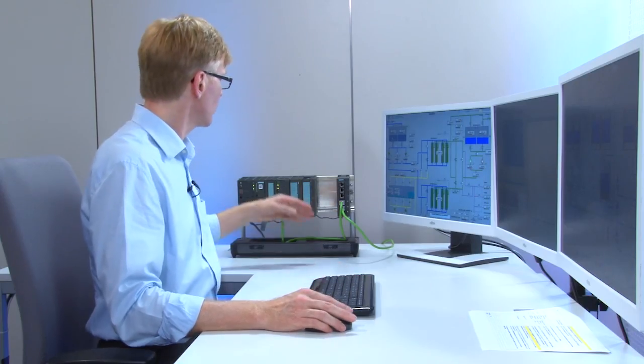As you can see, in just a few minutes we have configured a WinCC control center and its basic functions and started it up using ST7cc. A majority of the elements required in WinCC were automatically generated by SINAUT ST7cc and created in WinCC. ST7cc automatically generated the WinCC picture variable, the messages and the archive variable. It also generated the station faceplates for operating and observing the telecontrol station. We will show you how to configure the associated process station with Step 7 and SINAUT ST7cc in another video.